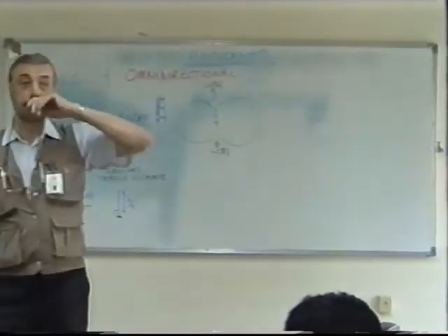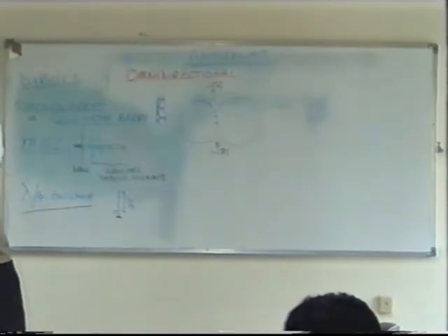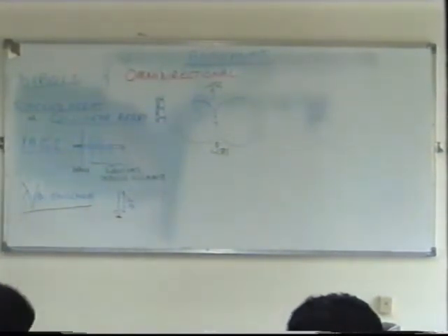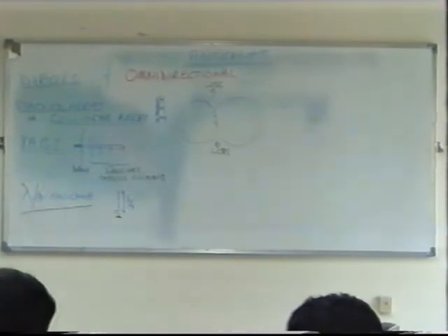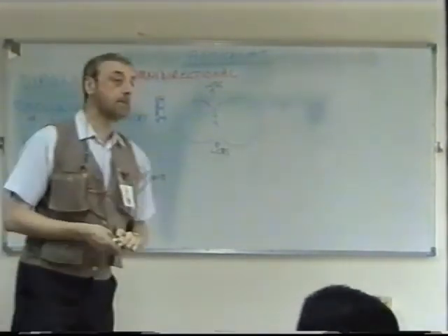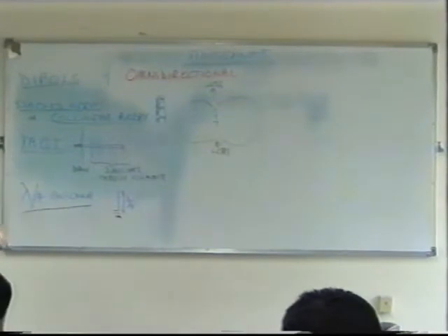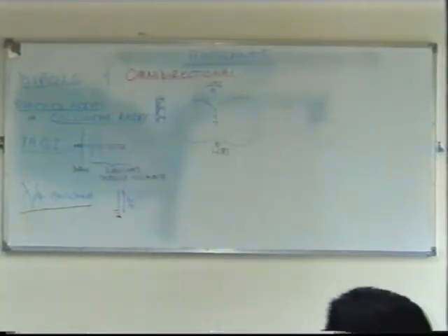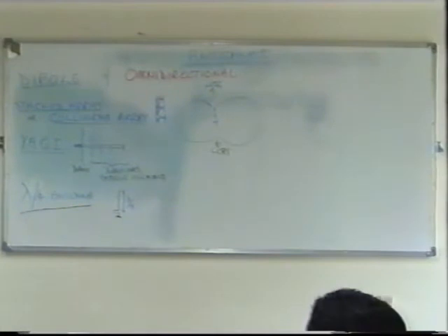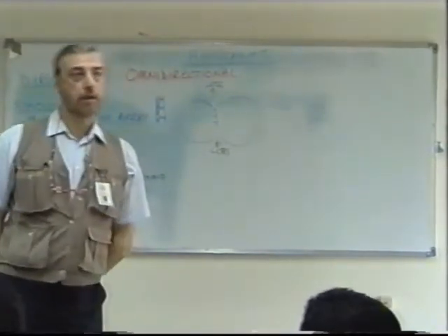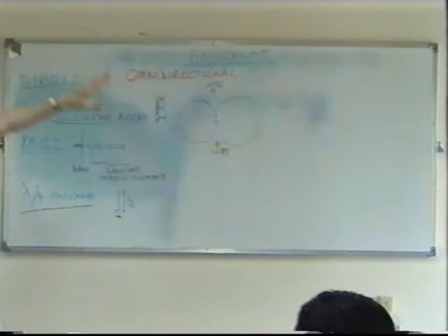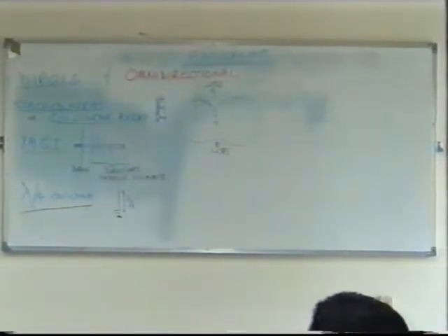Well, all the repeaters will be outside. They're not inside. Although they do have repeaters in some buildings, like in the New York Stock Exchange and places like that, where people are using cellular phones a lot, they'll put a repeater in the room for the cellular telephone. But generally speaking, if your repeaters are outside, what they call the base station, on a roof somewhere, and you're inside a building, it gets more and more difficult to receive the signal at that frequency, because it's UHF.